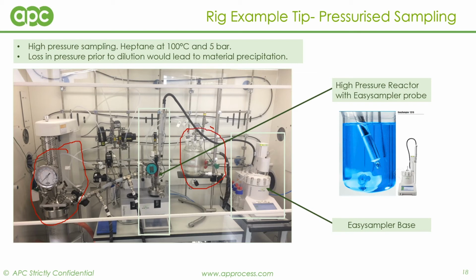Now, to monitor this process, we included an additional vessel, which is a high-pressure EasyMax in the middle here. We included this because we wanted to implement an EasyMax probe or an EasySampler probe to monitor the supersaturation of the extracted solution before it hits the cooling crystallization. It's really important that we include this online monitoring because otherwise it'd be very difficult to gain the information required to complete a focused and informed optimization of the process.